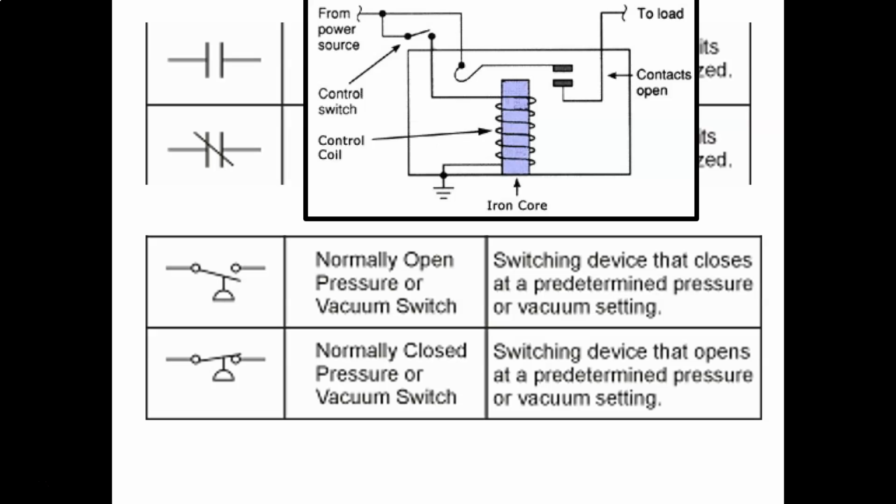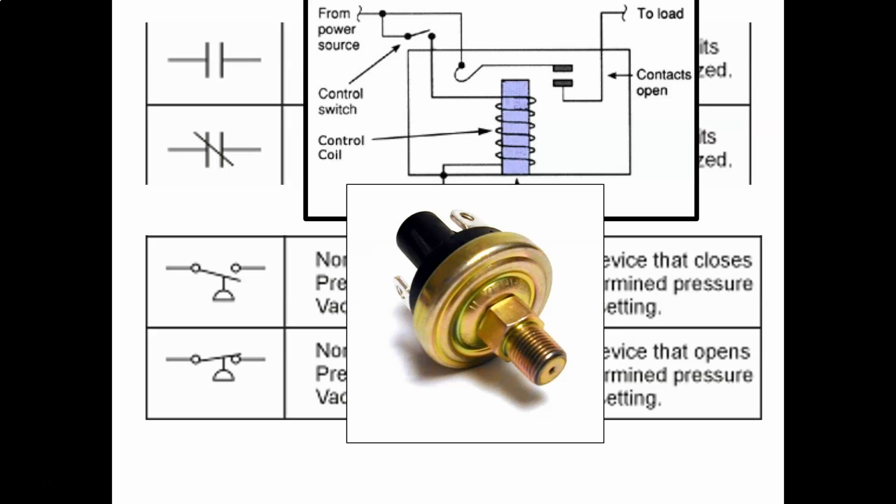Okay, so in this case, there's no pressure in whatever this is, so the device is just going to be hanging there. Pretty much you're buying that device off the shelf at Home Depot. It's not actually hooked up into a circuit yet, or put in a tank or a vacuum. It's just sitting there, so you've got to look at that state, and that's going to tell you whether it's normally open or normally closed in normal conditions.